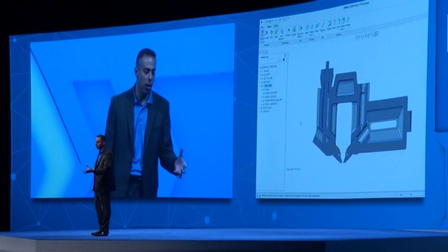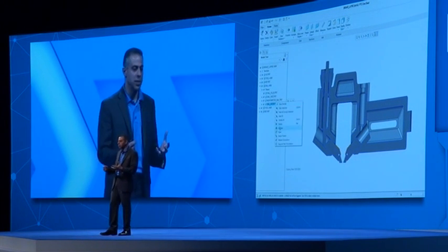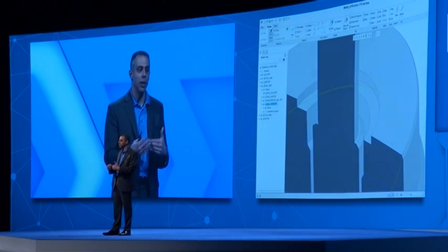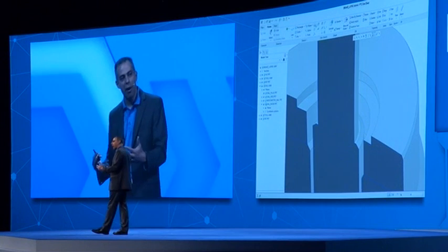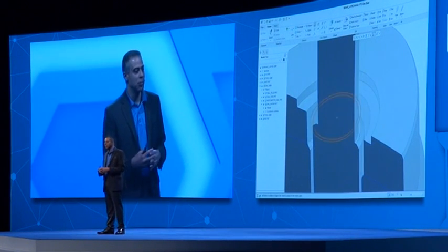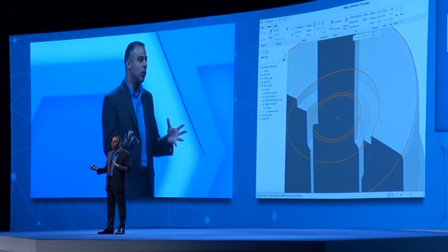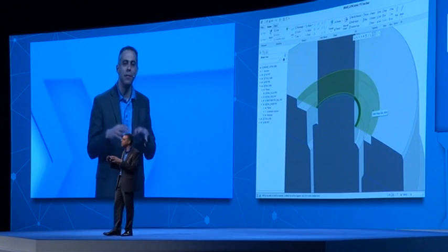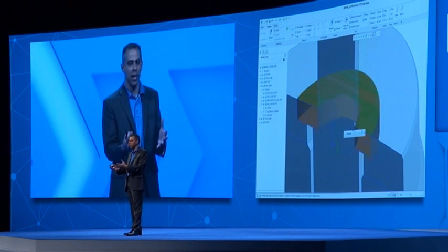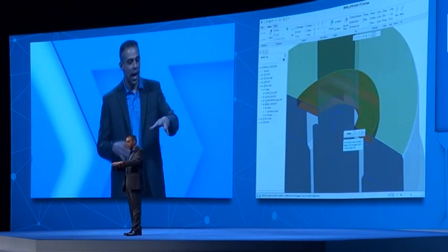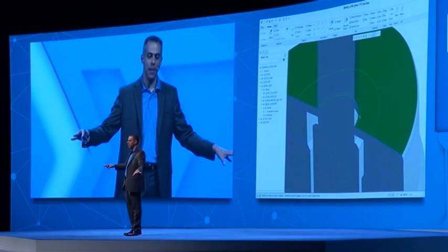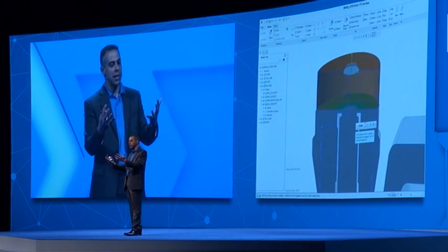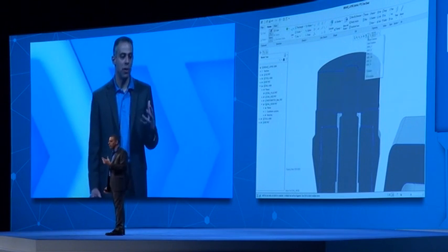We're going to add a new component in the assembly context. You'll notice there's quite a bit of work in this video working in assembly mode, in cross-section mode, while you're in assembly mode. This is a really nice paradigm for direct modeling users. They like to work in cross-section mode. It's a nice way to visualize your design. And even though you're working in cross-section mode, we're creating real, fully revolved geometry here. It's just a nice, convenient way of visualizing what you're working on. Okay, so you see, I've made this new component. I'm using some surrounding geometry from the parts around me to create 2D elements that I can then extrude up to create 3D elements. This is all new geometry in my part.